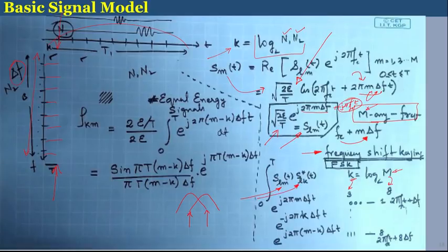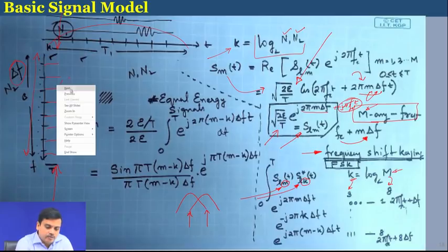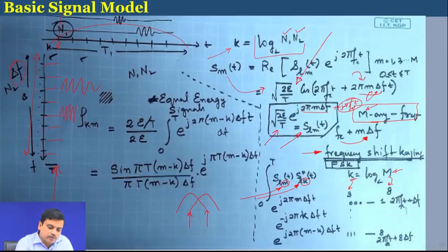So, L indicating the low pass equivalent, M is the mth frequency, K is the kth frequency, indicating two different signals, that is the mth signal or the kth signal. That means, either I choose one particular frequency over here, or I select another frequency over here. So, it is between these two. In the time interval T, which is the symbol duration, we would like to see that these two signals are orthogonal, like we have two passband signals which we would like them to be orthogonal.